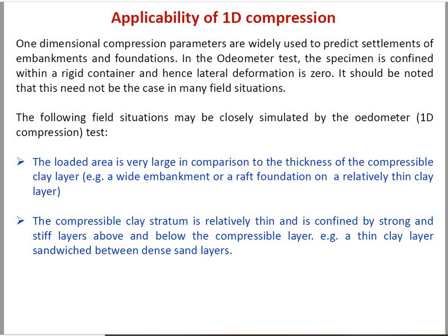Also, you are providing saturated porous stones on the top and bottom of that particular clay layer specimen. That means you are providing some compression from top and bottom. Due to that stone, there is some compression. Obviously you are applying the load, that is another thing. So due to these conditions, you will not get the actual field situation. That means the results you obtain from the lab will not actually simulate the field condition.